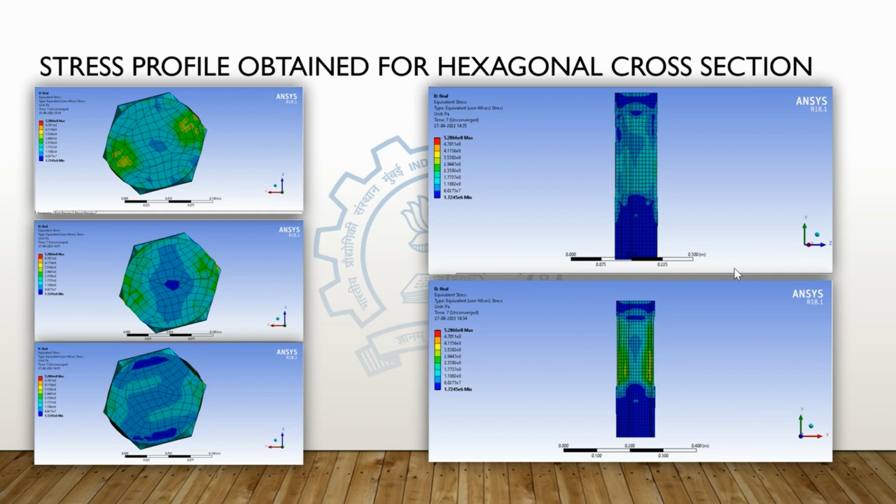So this is the stress profile developed. Now aluminium's yield stress is somewhere around 2.3 into 10 raised to power 8 pascals. If we see this graph, on the side there's a color coded list. Basically, green represents 2.35 into 10 raised to 8 pascals, and any color above green represents stress higher than that. So any color above green means that plastic deformation has already occurred there.